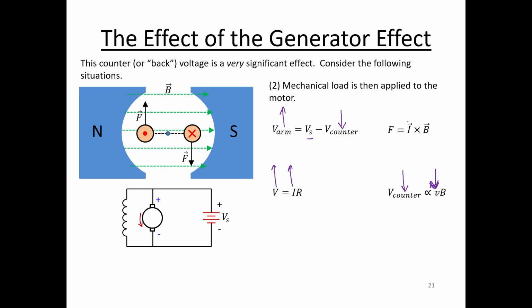current. And if you're going up in terms of its current, remember B is constant when you have a field winding in parallel with the source and the armature. So if the current goes up, you get more force on the rotor, and that means more torque.